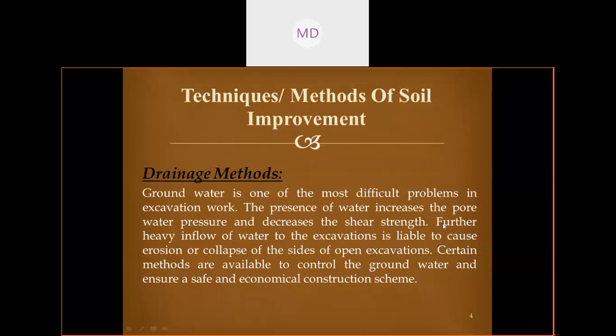Then further inflow of water to the excavation is liable to cause erosion or collapse of the sides of open excavation. That is what I have told just now. Certain methods are available to control the groundwater and ensure a safe and economical construction scheme. So there are various methods available, like electroosmosis is also one of the processes. Then there are other processes also.